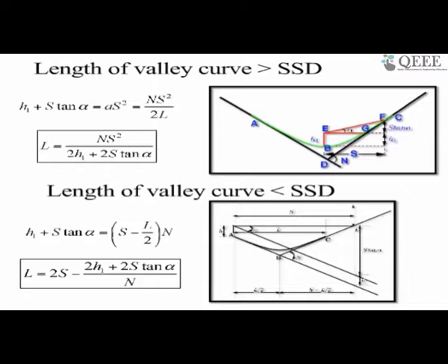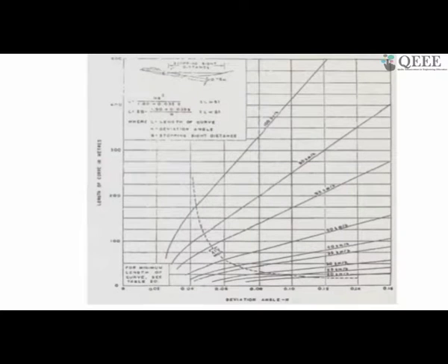And these softwares actually do all the calculations, whatever we learned here, in the background and provide the highway. As a design engineer, we need to select the proper point of intersection where the curve is going to be there, and we need to provide the proper vertical point of intersection where the vertical curve is going to be there.